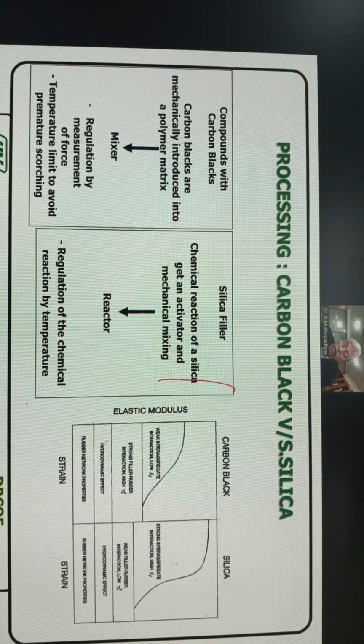So in case of silica silane mixing, one has to know as a compounder what is the dose of the silane or the ratio, and also the mix equivalent, the time to get the proper homogenization or the reaction to be completed. Time and temperature is very, very important, whether it is 142, 150 or 155 degrees centigrade, what is the mixing time to see that the silanization reaction is complete.